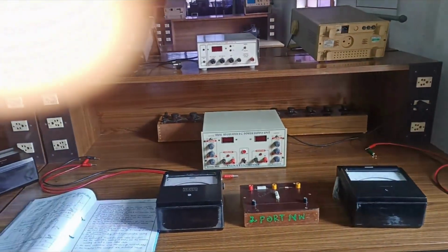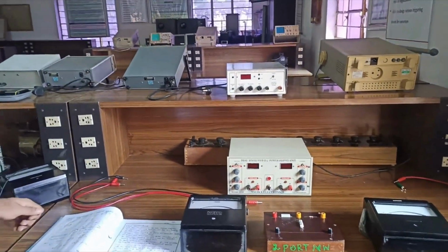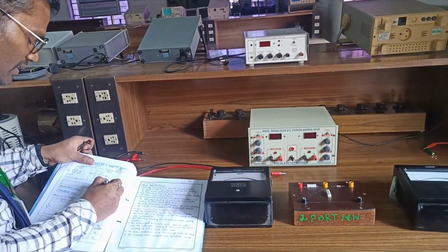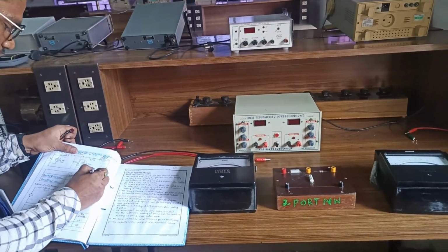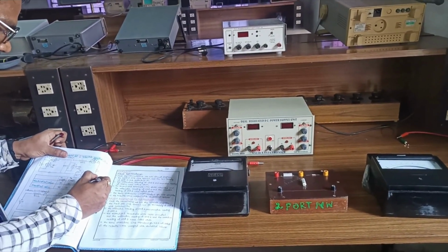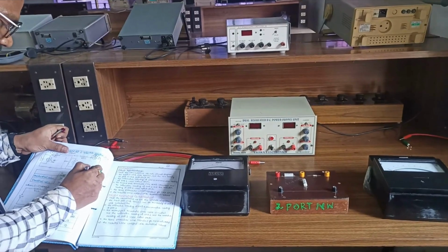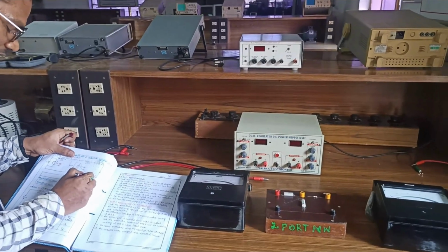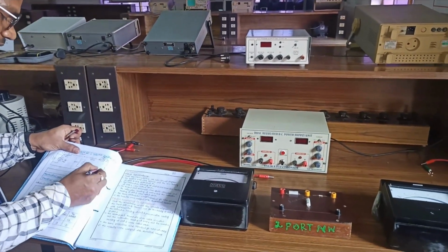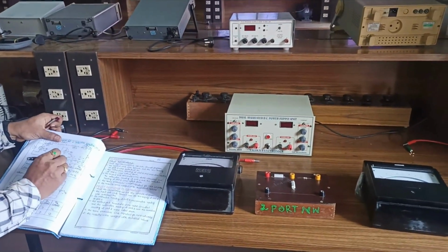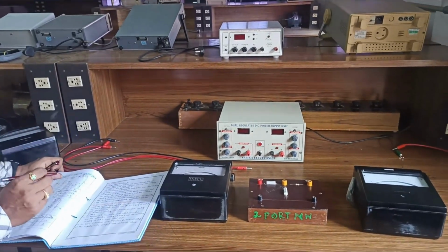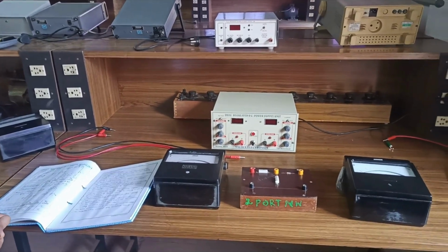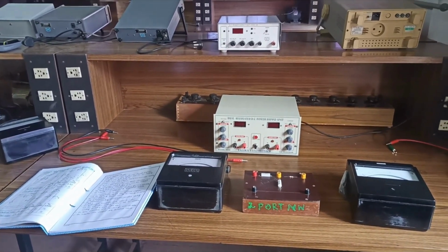So why it is called H parameters means here we have multiple parameters. Here you can see, V1 by I1, this is nothing but H11, units are ohms. H22 units are mhos. But H12 is V1 by V2, no units, and H21 is I2 by I1, current gain, so no units. Therefore, these don't have any unit. H11 is ohms, H22 is mhos. Now we want to find these multiple parameters, which are also called H parameters. Now let us try to see it.